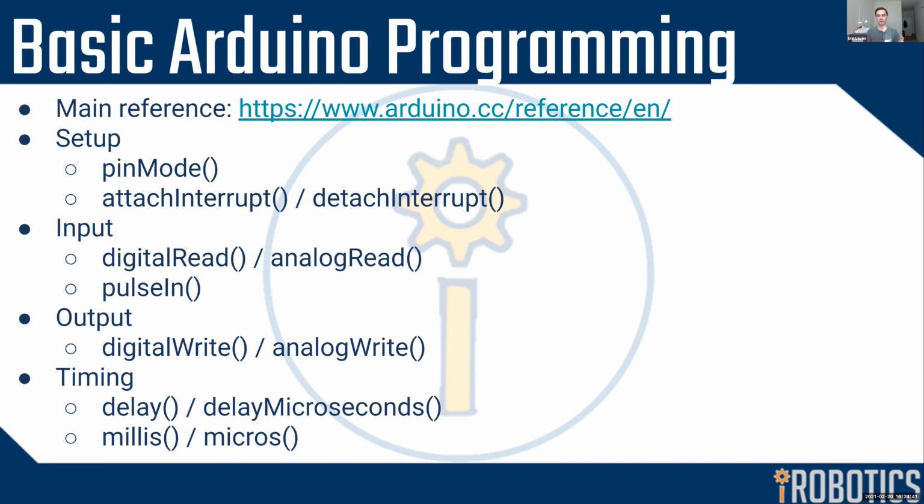That'll run it for 30 milliseconds and then turn it off. And then what the millis and micros functions do is they give you a number of milliseconds or microseconds since the microcontroller turned on. There's an example a bit later of, I want this code to run every 10 milliseconds. You watch the milliseconds as this function keeps returning them, and after it hits 10 milliseconds, you run the code, and then you wait for another 10 milliseconds. That lets you loop and do things over and over, but not every single time the function loops.